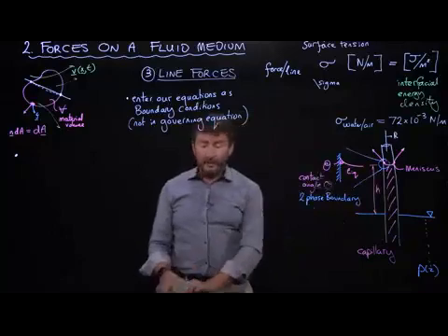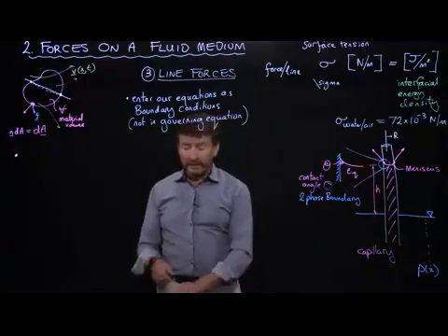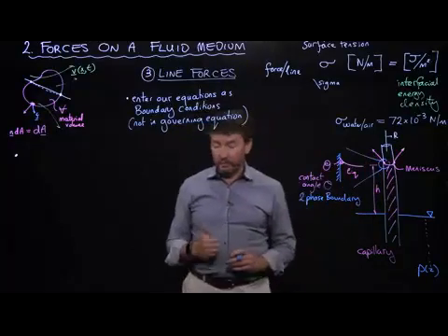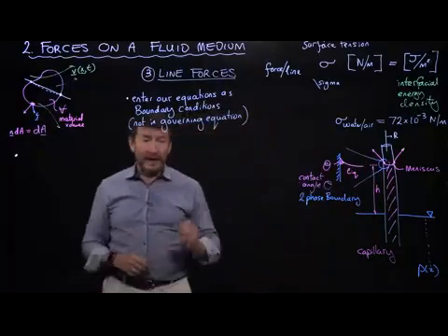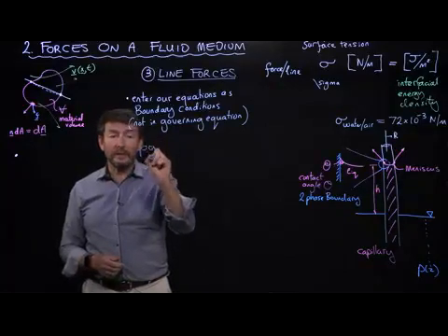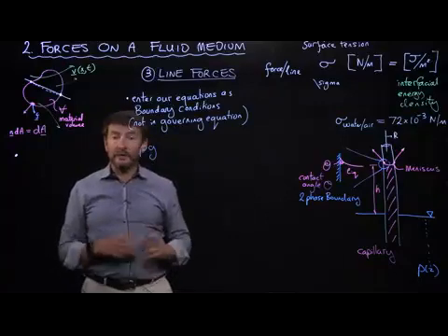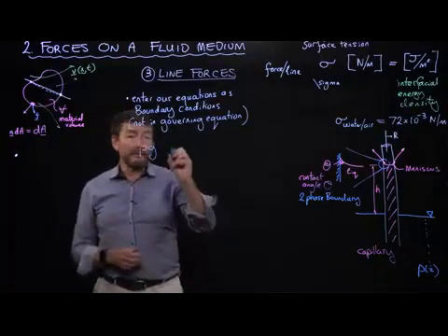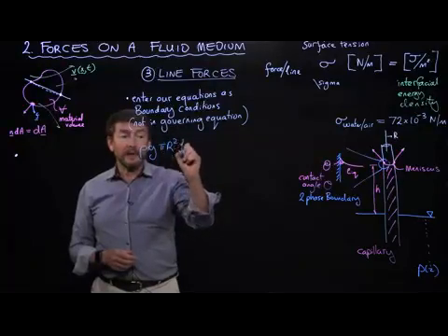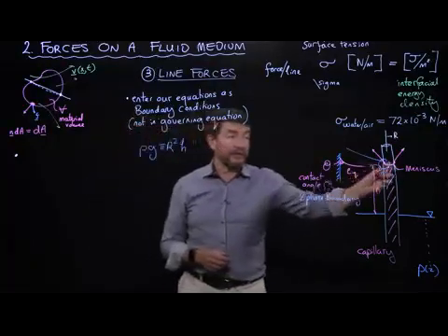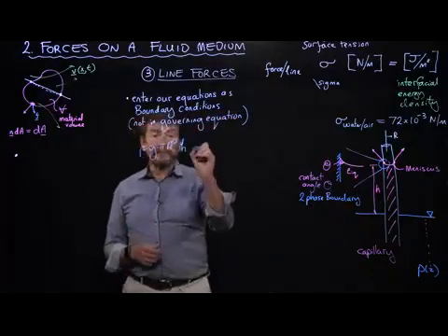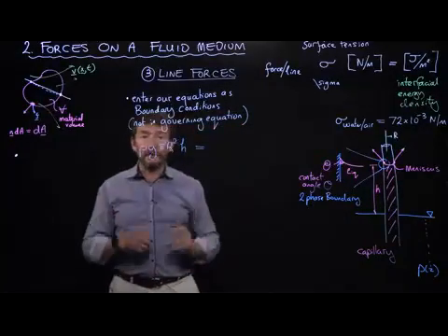And when the system comes to equilibrium, then we'd like to think about what the set of forces are. First of all, the force that's acting downwards is a body force. The body force acting down is going to be rho times g times the volume of this element. The volume of this element would be pi r squared times h. Okay, so that's a cylinder of material. It's acting down, and this must be balanced by the force that's pulling up on it.